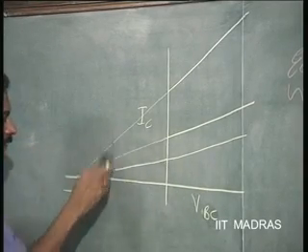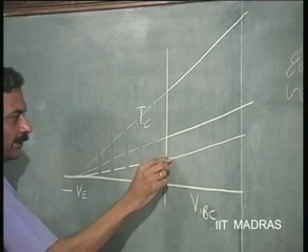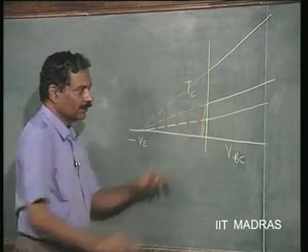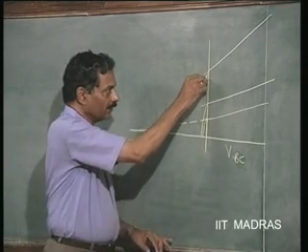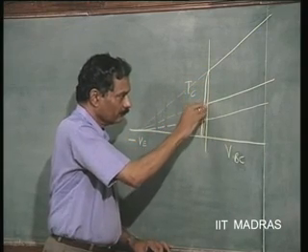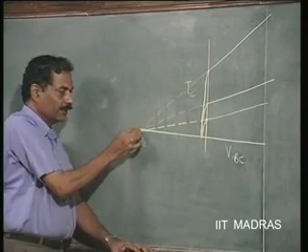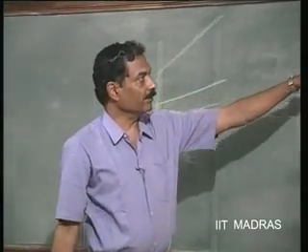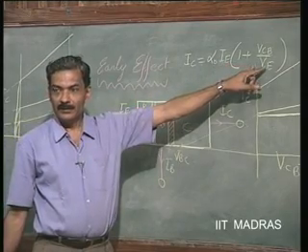These are going to be extensions; otherwise the actual characteristic is different, because in this region the transistor goes to saturation. So, this will be the actual characteristic of the transistor. These extensions join at a particular point, and that is an important voltage which is called early voltage.